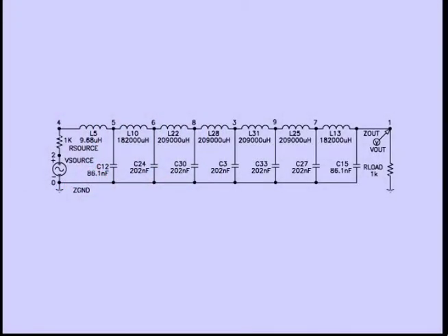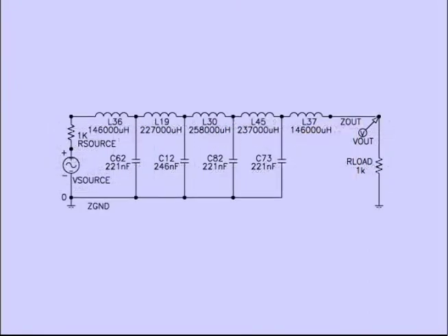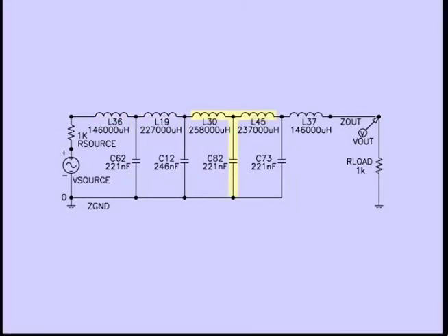Since genetic programming is a probabilistic algorithm, different runs produce different results. The previous evolved circuit is a cascade of 6 identical symmetric pi sections, while the 100% compliant solution evolved on another run consists of a cascade of 4 identical symmetric T sections, each with the numerical values specified in Campbell's patent.